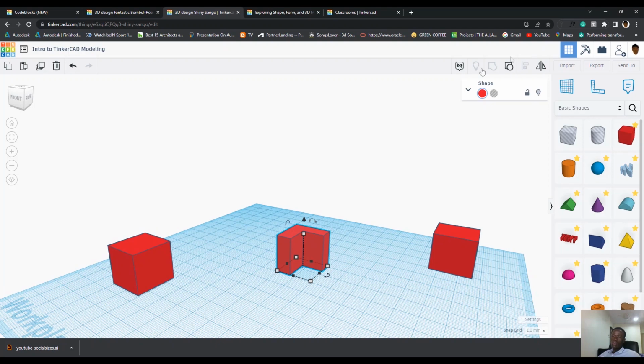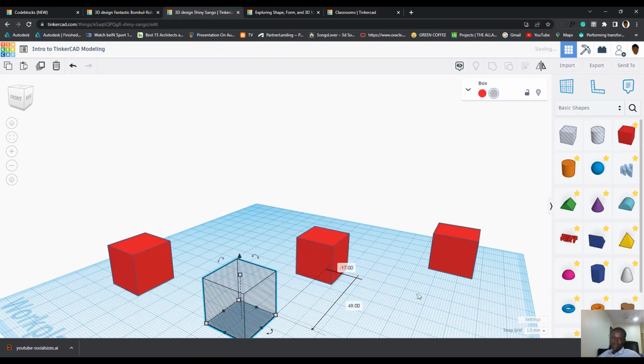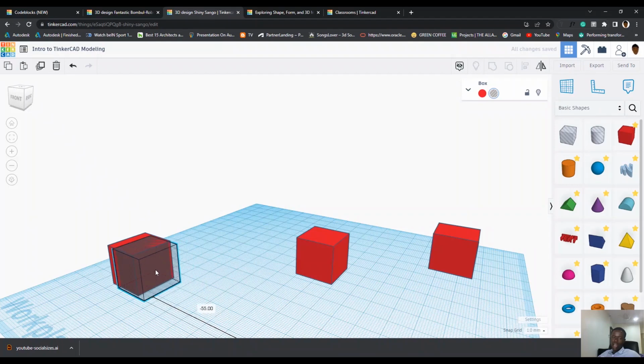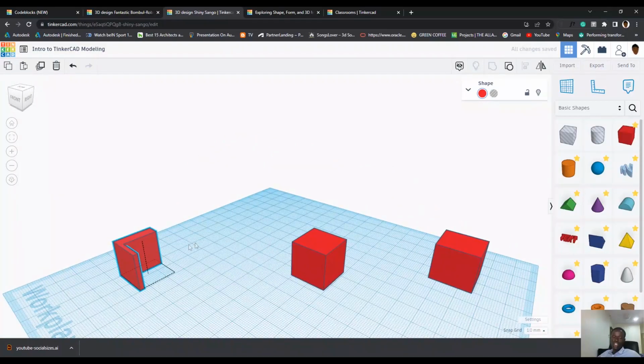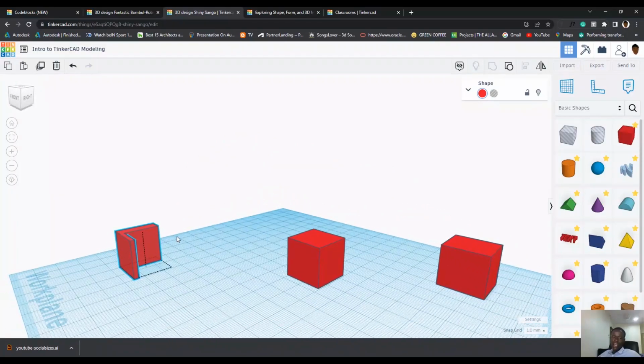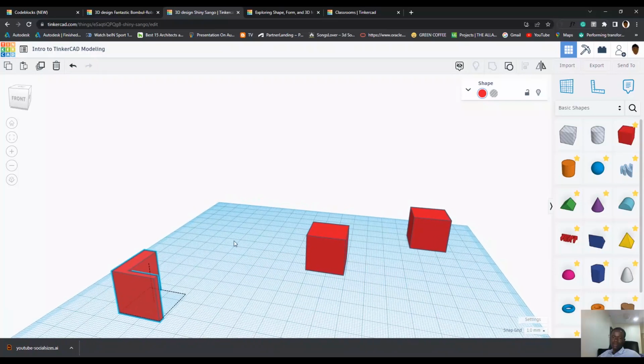Basic 3D shapes. So we have the group icon that groups whole object and solid object together, and then I can use the next icon beside that, which is what? Ungroup. Immediately I click on ungroup, you can see it restores back to what? Default. Now I can move them apart, or I can even add my whole object to another object on the workspace, and then select both of them again and group them together using the tool again, and then it cuts off. It removes the portion at which it is touching the solid shape, and a complex 3D object is created for me.